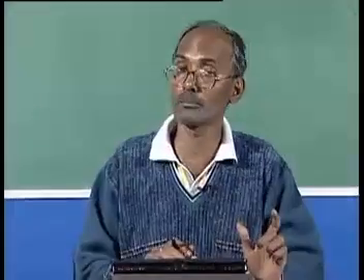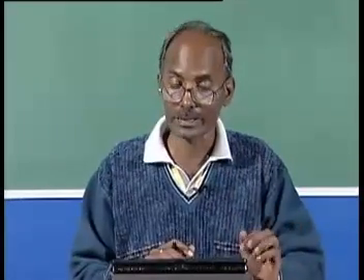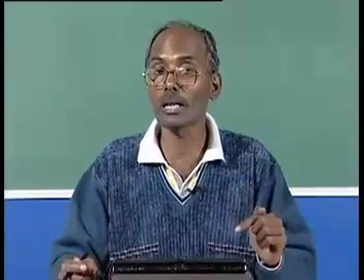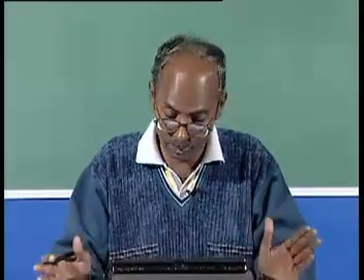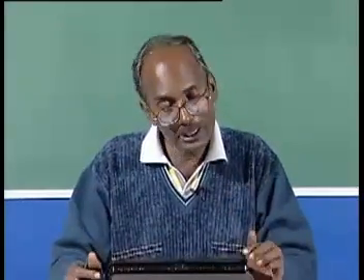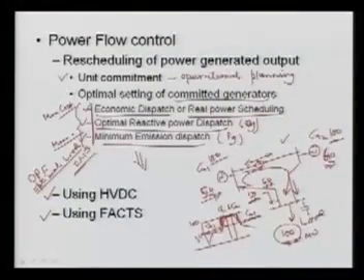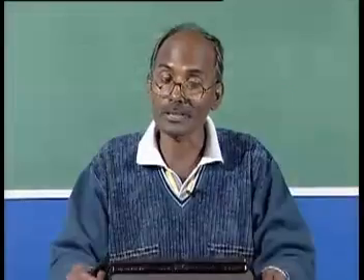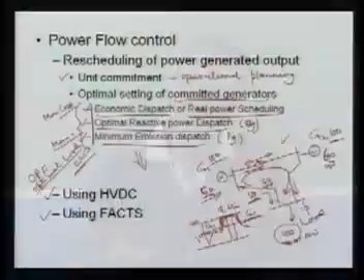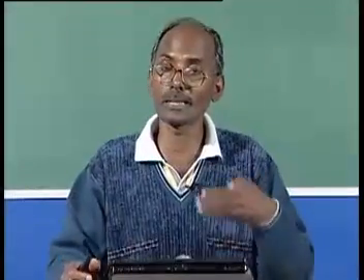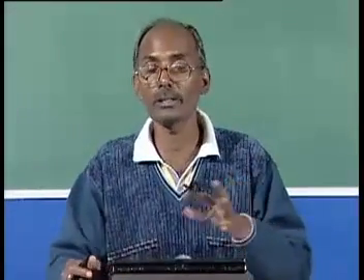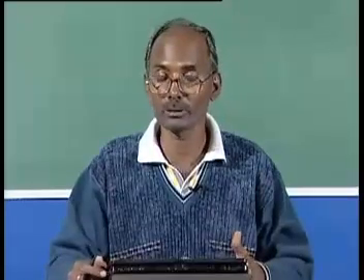Already I have explained the basics of the FACTS controller, that they can control the power in any line or in any subsystem or the designated corridors. Similarly, HVDC can also do power flow control. It can even reverse the power in the other direction, meaning power which was flowing here can be reversed. So it has the capability to do any sort of control, and that is sometimes very, very useful.